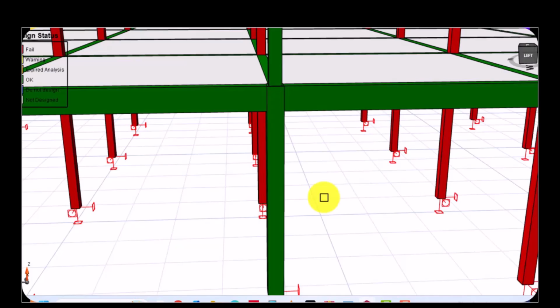So concrete is very strong in compression but very brittle. Without confinement, once the crack starts, failure is very sudden. Confinement on its own increases the strength of the column. Let's take that. It also increases ductility and the warning before failure. This is very important, the warning before failure. This deformation does not happen in one day. It shows signs before failure.